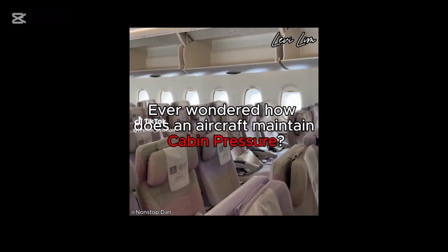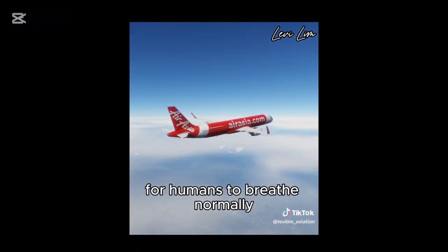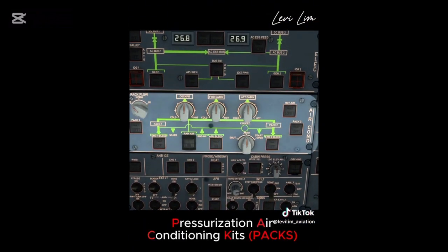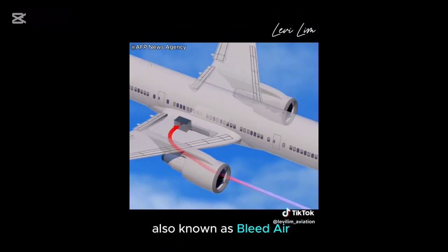Ever wondered how an aircraft maintains cabin pressure? Commercial aircraft cruise at high altitudes where the atmospheric pressure is too low for humans to breathe normally. To maintain a pressurized cabin, aircraft are equipped with pressurization air conditioning kits, PACs. Initially, hot and high pressure air is taken from the compressor section of the engines, also known as bleed air.